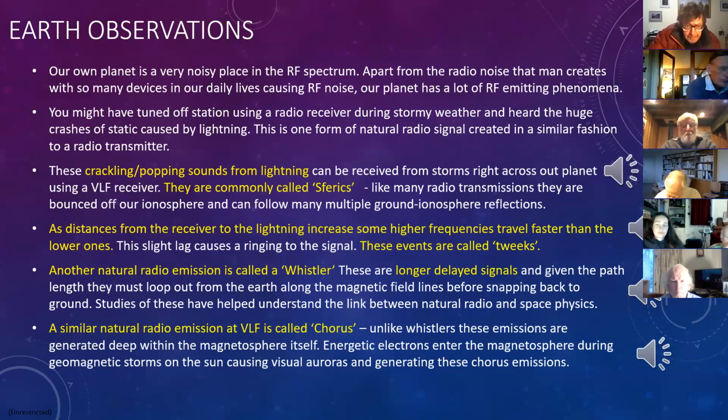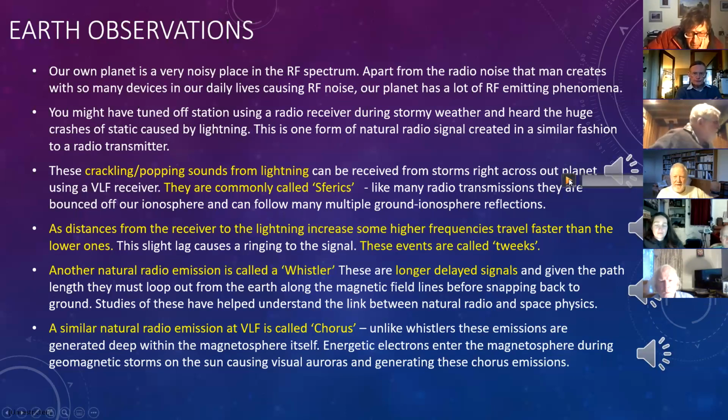If you go further down the radio spectrum into the VLF area, with VLF meaning very low frequency, down into the tens of kilohertz range, it's quite quiet down there in some places once you get out of the way of switch mode power supplies and things like this. If you've got a decent antenna and a dedicated receiver, you can pick up these pops and crackles from lightning, and you can receive them all the way across the globe. These are called spherics. Let's see if this will play.